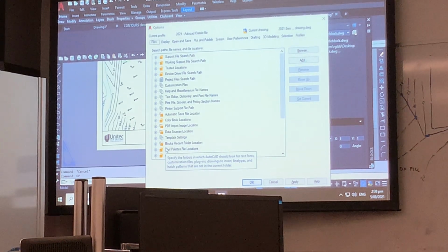Also, the XREF paths for cross-reference drawings, so it could be a survey drawing that's put somewhere, and that'll come into the background of your drawing as well. So you can actually have other drawings inside your drawings, but they're not really there, they're just pathed in temporarily. When we give AutoCAD to clients, we tend to package it all up in one big package, including your logo and XREF drawings, and we send it off a bit like a courier parcel, so that when they open it, all these things come into their drawing.